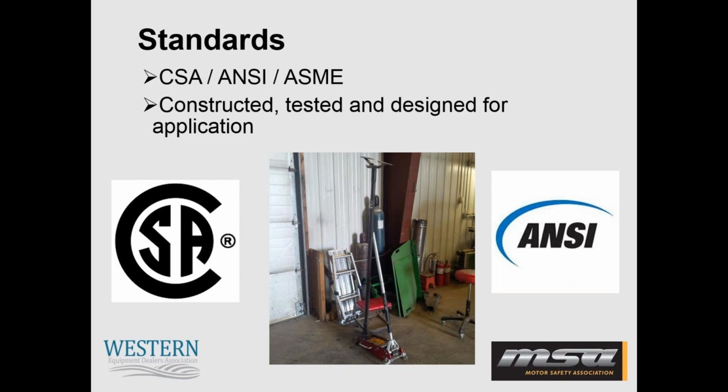And the flip side to this is, if there's no rating on it and there's no capacities or engineer approval, this is not okay to use at your workplace. And also, don't modify your floor jacks or jack stand devices. I took this picture at a shop here recently, and they added this attachment to their floor jack as seen in the middle picture, and it was home built and it did not meet any type of engineering approval.